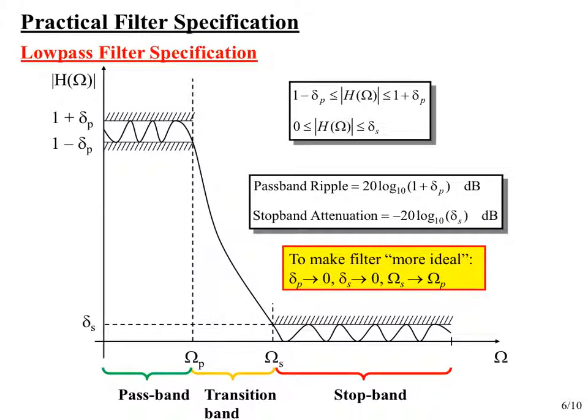And here's how we typically spec these. So the specs that we're trying to meet show how much we're willing to give up from the ideal filter case. So for a low pass filter, and I'm really only showing here from 0 out to pi, and because I'm speccing this for the magnitude response, this will be an even function, so you'll know what it looks like from minus pi to 0.